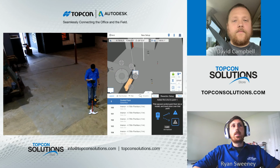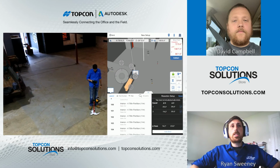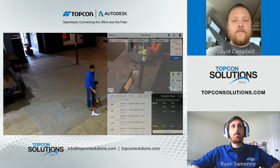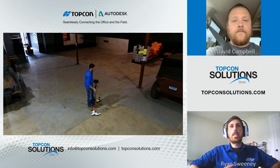Once we do that, the LN150 is going to tell us our residuals on that resection, which you can see here in the BIM 360 layout app. And if those residuals are good for you and within an acceptable tolerance, you can say, okay, great. And now we can go on and lay out into the next step.